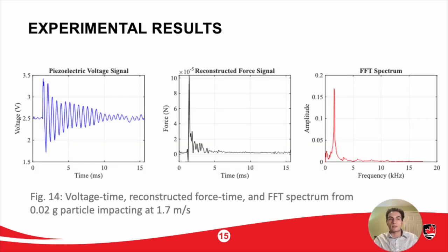So here are some experimental results. These three plots basically characterize the piezoelectric response. On the left is the raw voltage response, and we see it's behaving just like a damped harmonic oscillator with the exponential envelope squishing that sine wave down. Next, we have the reconstructed force signal, which is obtained through deconvolution of that voltage and the impulse response. And then on the right is the FFT spectrum of the voltage signal.